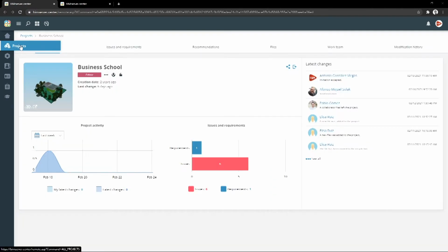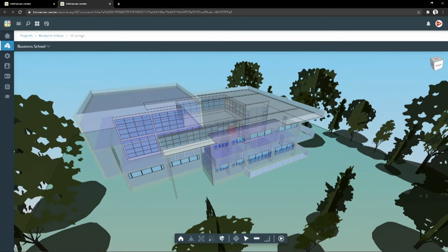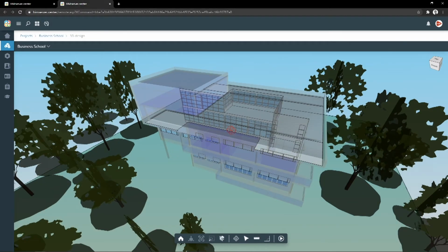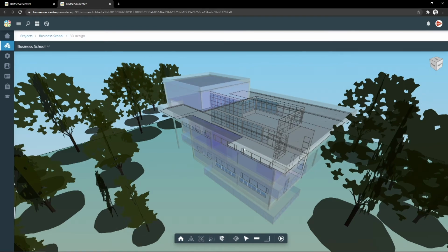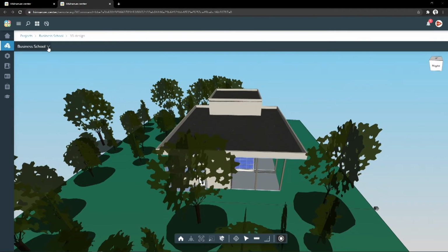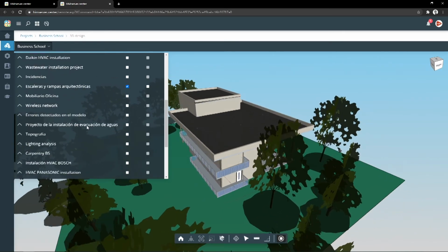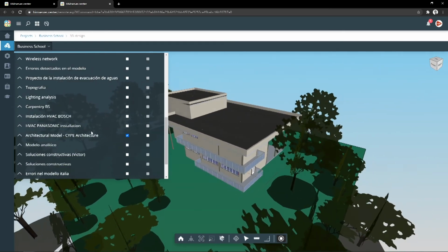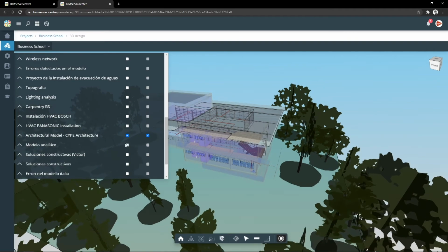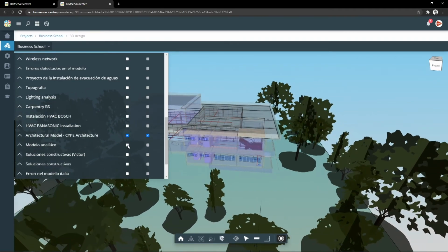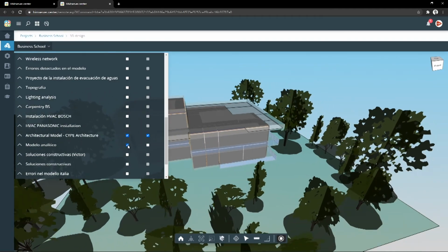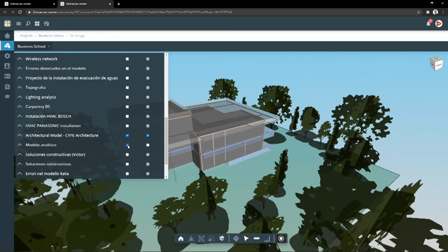The first step to follow in order to conduct an energy analysis, or a BEM, a building energy model, is reading an architectural model where its spaces and limits are defined. This model may come from modelling tools such as Cype Architecture, IFC Builder, Revit, Archicad, Allplan, etc., and must be exported in IFC format and linked with a project on BIM Server Center.